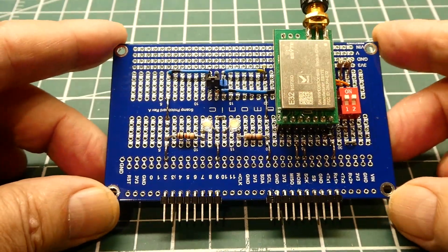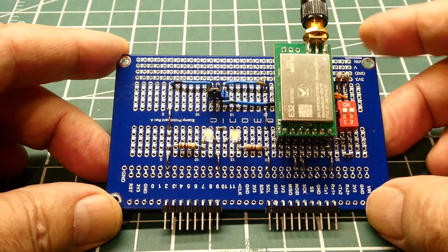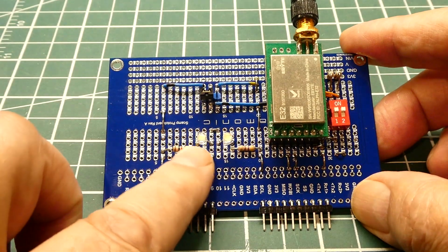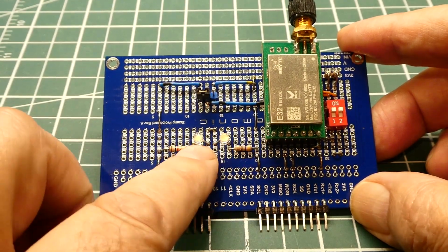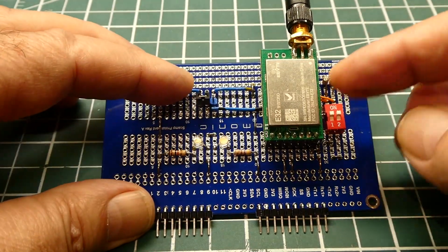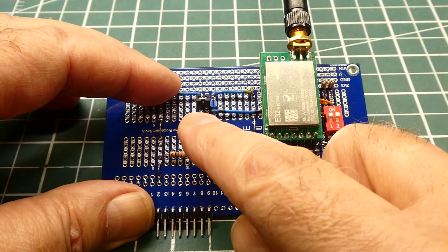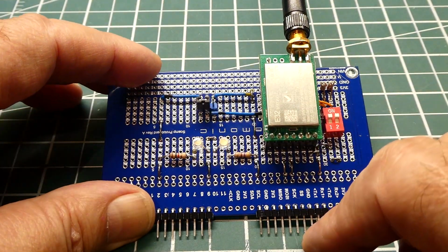Okay, I built my LoRa interface board using a SCAMP3 protoboard. And I'm using it as my development board also. I have 2 LEDs. This is my 5 volt LED. This is my 3.3 volt LED, so I could tell if I have those 2 voltages on the board. Then I could select what voltage I want to feed my LoRa module by this jumper here. If it's jumper to the left, that's 5 volts. If it's jumper on the right, that's 3.3 volts.